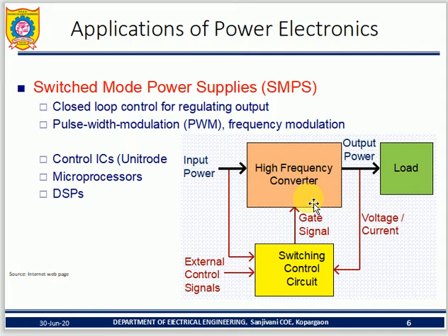For example, you can see an electrical fan regulator turning into an electronic fan regulator. The electronic fan regulator looks like a small switch, with a point type or without a point type. So the space occupied is reduced. How is it reduced? When you go for high frequency conversion, your size or space occupation is automatically reduced.